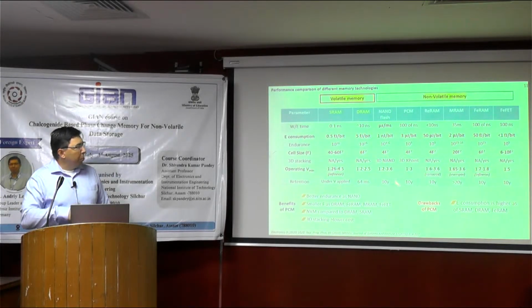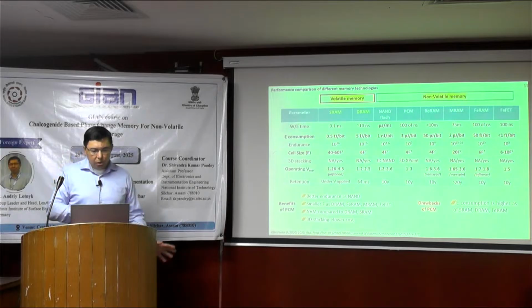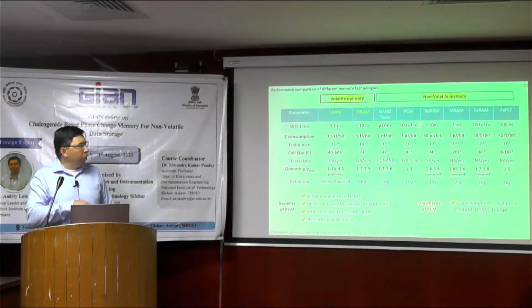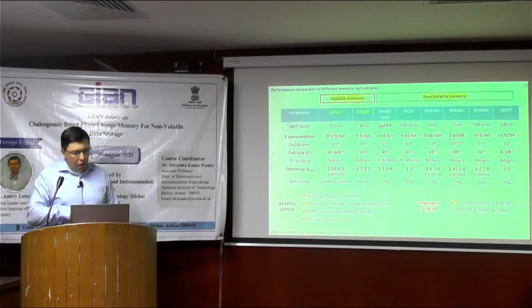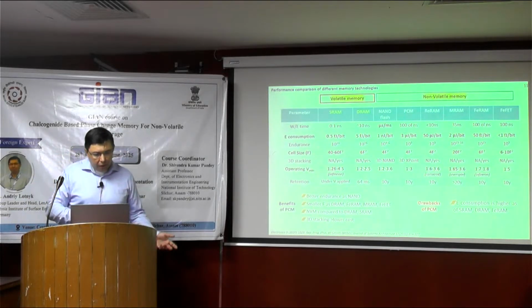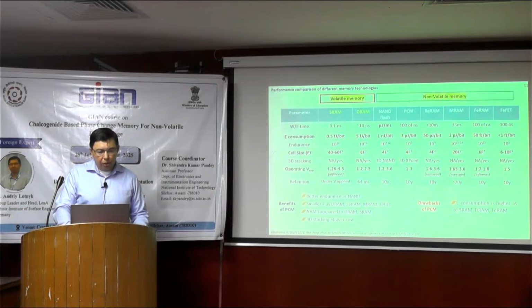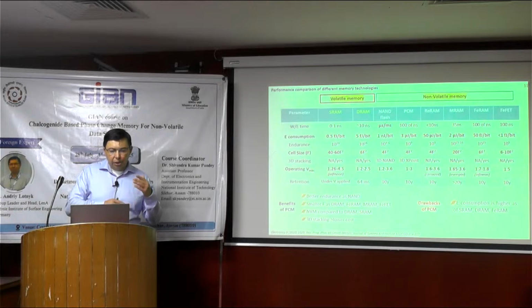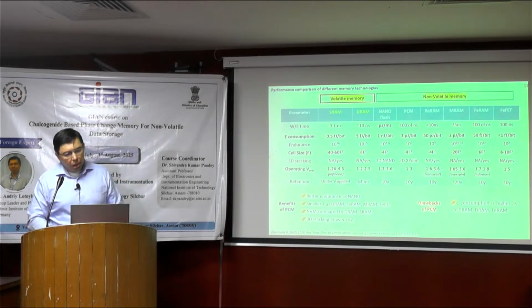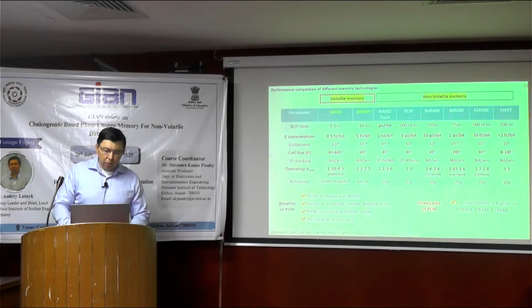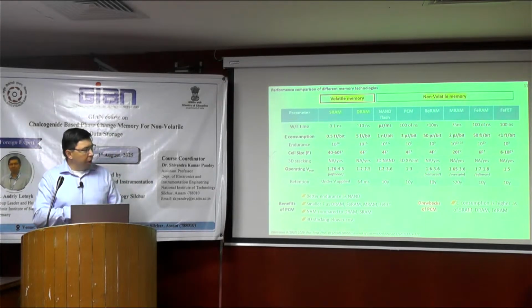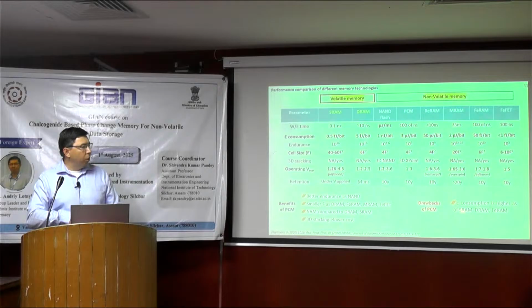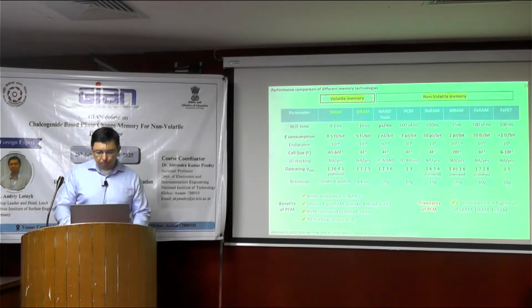For our memory technologies, it's the 10 years which we need. So if we compare phase change memory with other technologies, we find that PCM has benefits like better endurance than NAND, a smaller footprint like DRAM, FRAM, MRAM, and FeFET, and it's non-volatile compared to DRAM and SRAM. It's also scalable in 3D, so it brings low cost. But there are still drawbacks of PCM, and one issue is the high energy consumption, higher than for SRAM, DRAM, and FRAM.